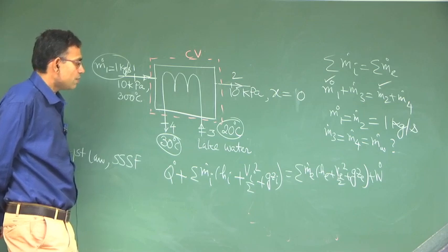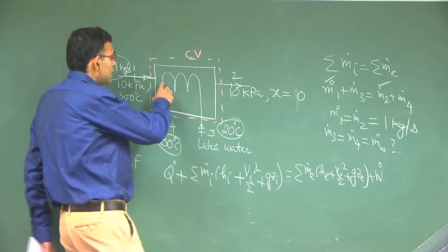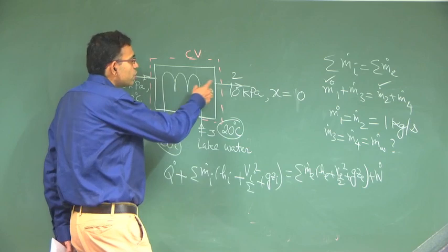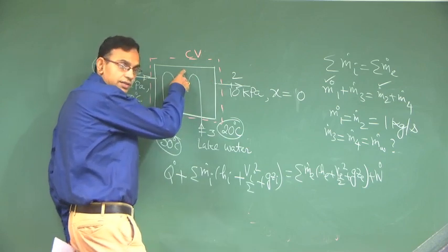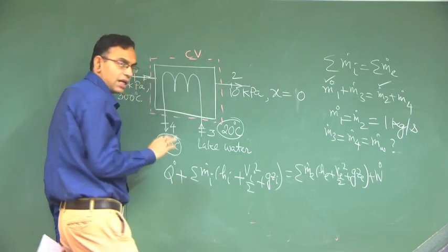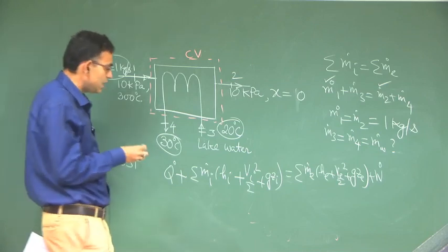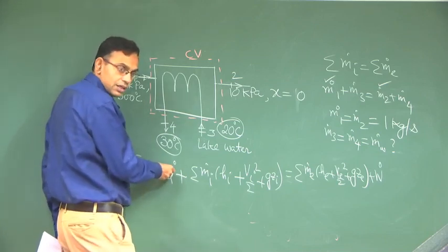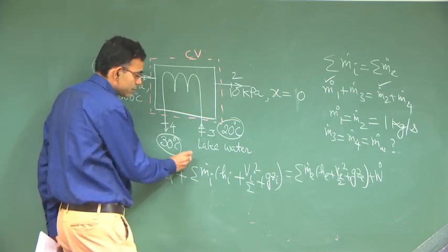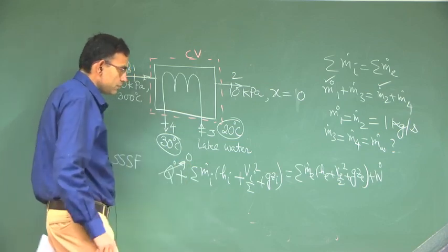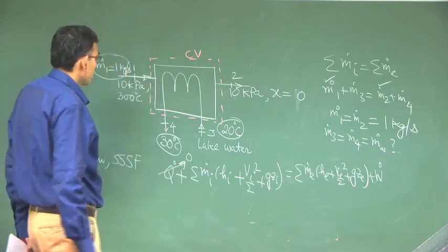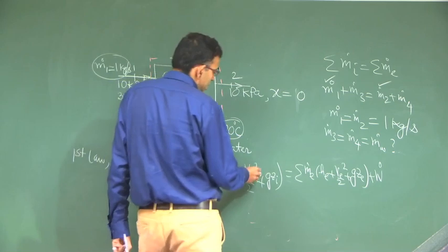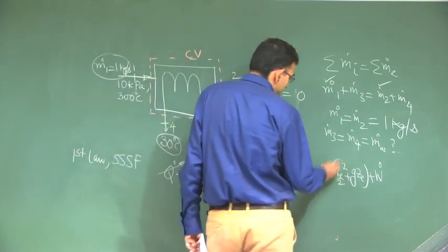First of all, in the heat exchanger there is exchange of heat between the two streams. So, there is no external heat transfer. By the name heat exchanger, do not get confused. So, this is 0. Then you can neglect the changes in kinetic energy and potential energy.